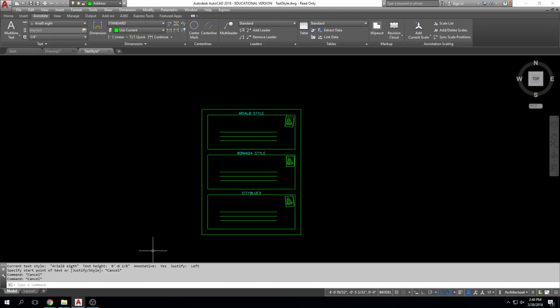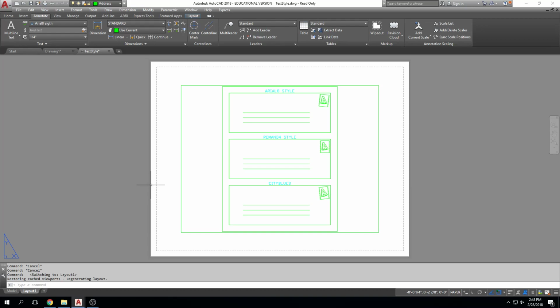by 400 foot house, right? It's going to be tiny. It's going to be microscopic. You won't be able to see it. You have a scale issue, right? So in order for it to be viewable and scalable, we have to size it up so that when paper space translates it down to scale, it's the right size printed, okay? So when you create your text in model space, AutoCAD may say, you know, to have an 1/8 inch text, when you print, it actually has to be 10 inches tall, so that when I scale it down by 48 times, right, to achieve a 1/4 of an inch scale, that it's the right size.